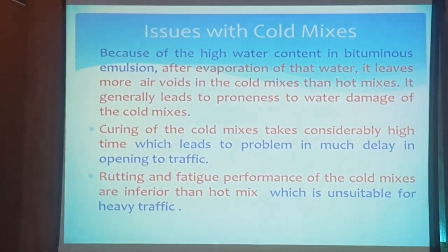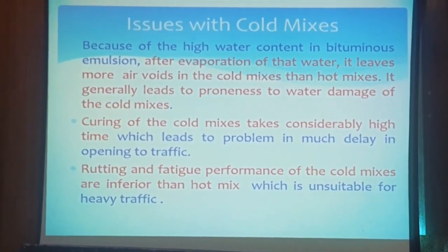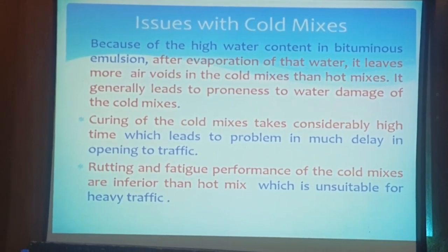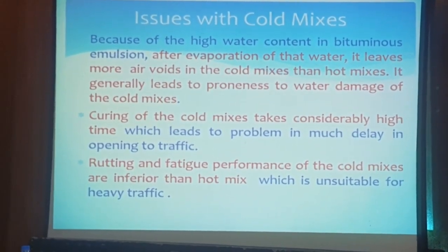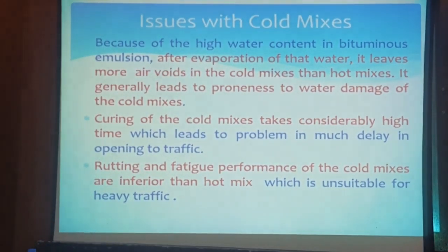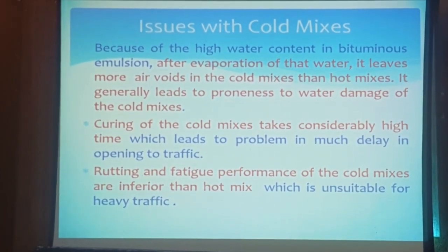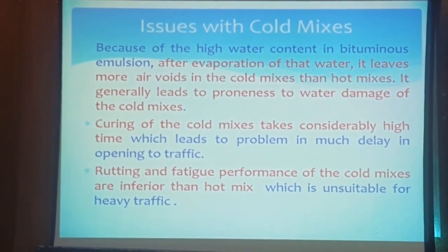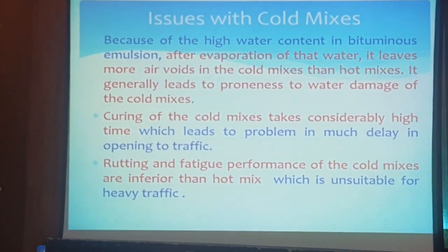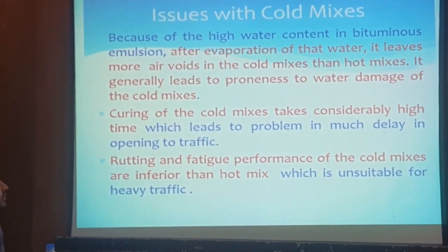The issue with cold mix is that it can be used for low volume roads, in village roads or PMGSY roads. There are a lot of applications of cold mixes. But with high volume roads, this is unfortunate, but quite true, cold mix cannot withstand high volume traffic. And for intense rainfall, where rainfall is very high, it is not that suitable. Rutting and fatigue performance of cold mixes are inferior to hot mix. So these are the issues with cold mix with high volume traffic.